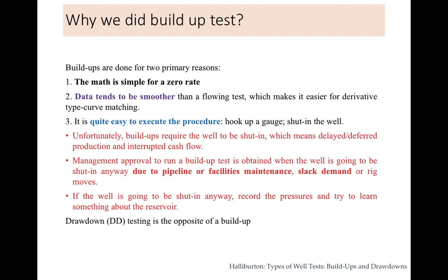Also, the management approval to run a build-up test can be easily obtained when the well is going to be shut in anyway, due to some kind of pipeline or facility maintenance, some kind of slack demand, or movement of the rig, right?